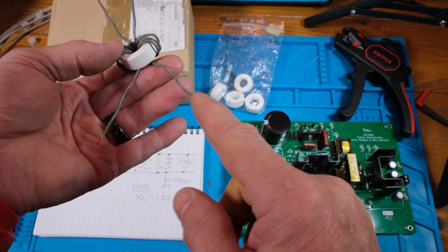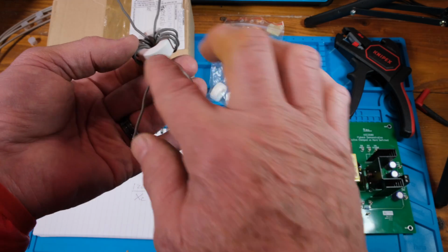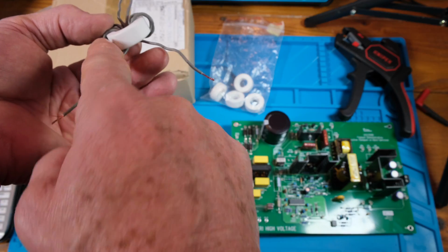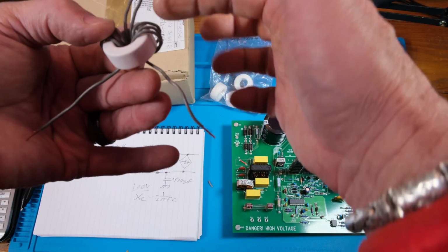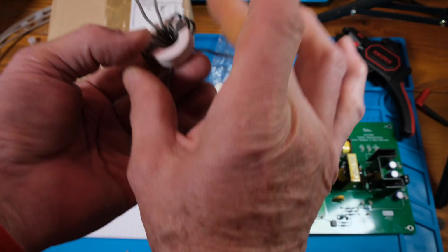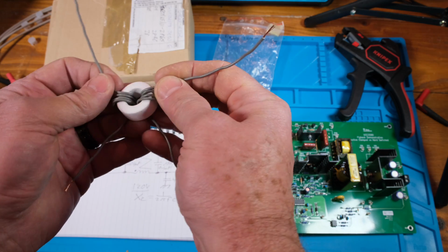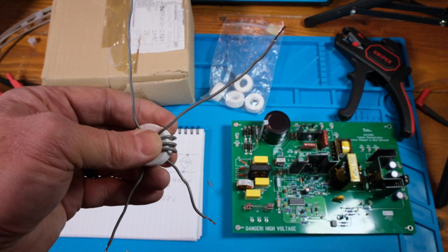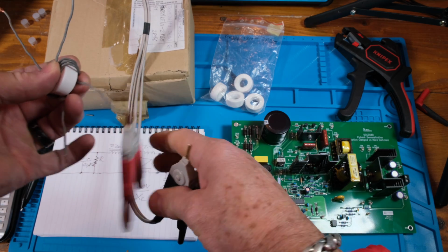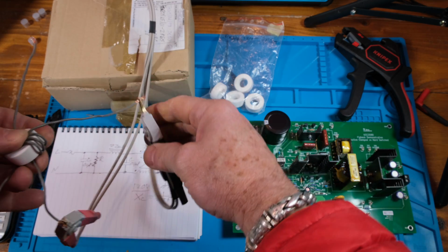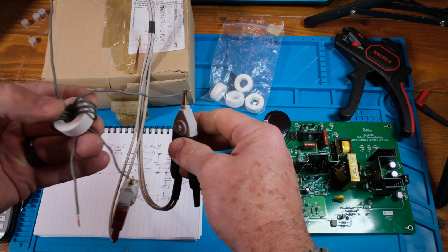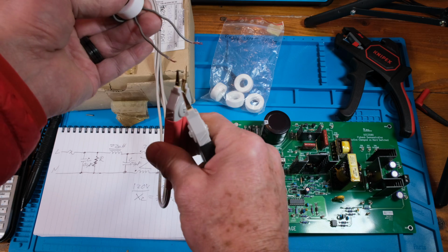But if it's common mode, and we have a signal coming this way, it goes clockwise. And if we go in this way, it looks like it's counterclockwise, but it's this direction. If we go around the core, that current is going clockwise, the same as this current. So those fields build really big and they add. Okay, let's measure it. All right, and measure one side of it. And wow, okay, I got about 2 microhenries. All right, then let's go on this one.